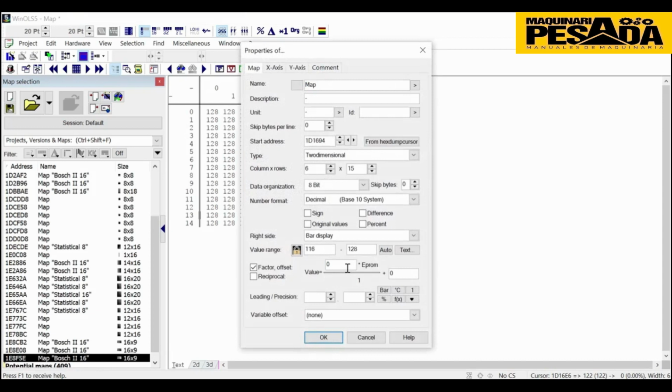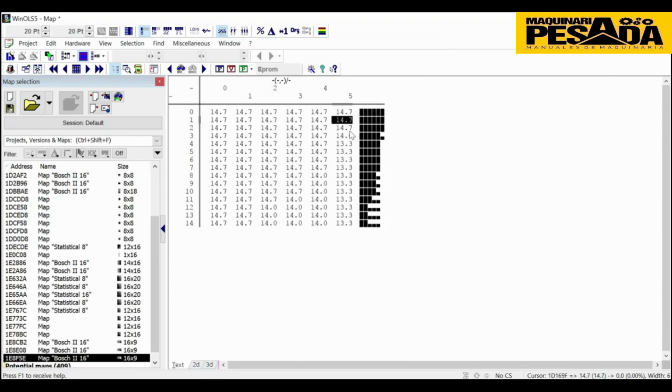If I'm going to remap for stage 1, okay, I can use the air fuel ratio around 12.7 for the best performance. You can even increase or decrease by graduation.